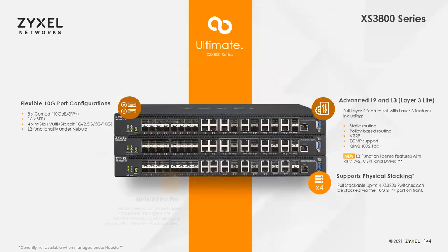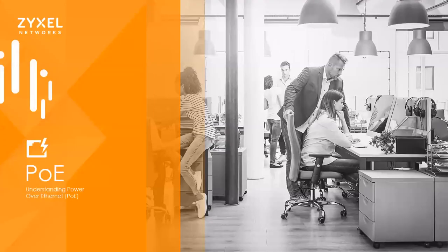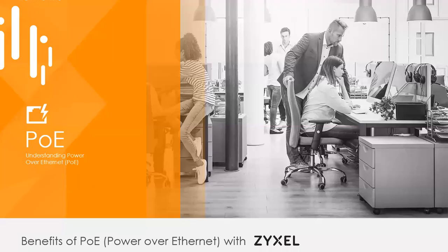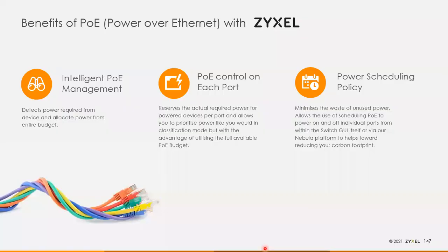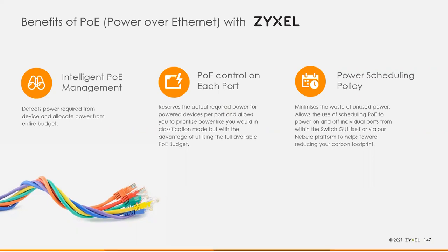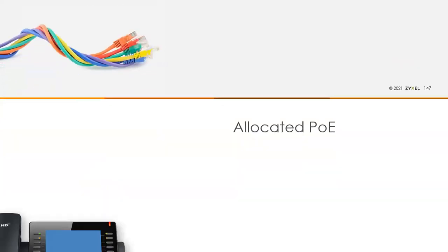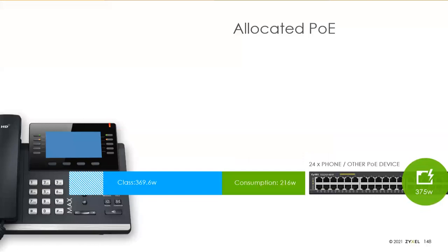So I want to talk briefly about PoE. We offer something that not all of our competitors offer, which is intelligent PoE management. Basically, this is the ability for us to actually look and monitor what each connected device in each port is using for PoE power, and then free up the unused portion that would normally be assigned to that device, so it can be used for other devices. So this allows you to more efficiently use the PoE budget on the switch.